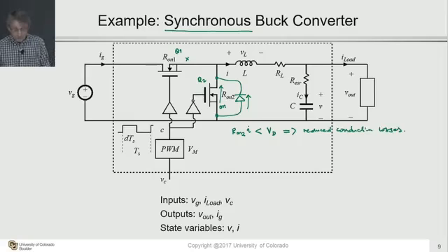And that's particularly important in cases where you're trying to make this converter serve as a power supply with a very low output voltage. The example that we are going to do in just a moment is going to regulate the output voltage to 1.8 volts, right? If you were to use a diode that has a forward voltage drop of 0.8 volts, the efficiency of that converter would be horrendous because that diode drop would be comparable to the voltage you're trying to regulate. Instead, you employ a MOSFET that has a very, very small on resistance and has the forward voltage drop in conducting current much lower than the forward voltage drop of a diode.